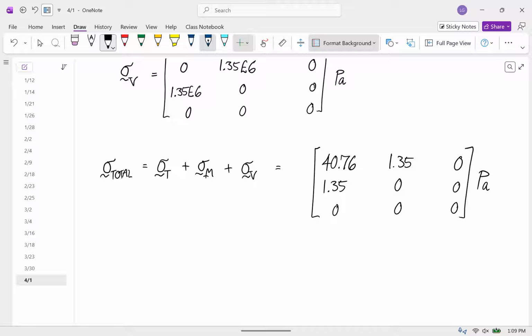And so now if this was a brittle material or there was some brittle connection point at this location, supposedly that's why you were interested in this one location, now you could calculate the principal stresses, use that to calculate the maximum shear stress, and see if your maximum shear stress exceeded some limit. Question?